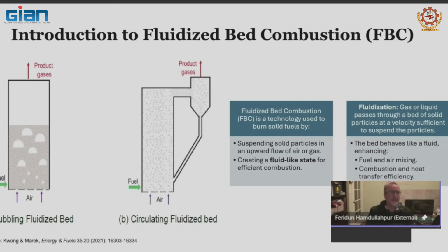Okay. In the bubbling bed case, again, you'll remember that any air that is in excess of minimum fluidization travels through the bed in the form of bubbles, and they enlarge as they ascend, and sometimes they coalesce, they get bigger. They are the ones that promote some sort of mixing in the dense bed, and above the dense bed in the freeboard region, they erupt and eject particles into the freeboard.